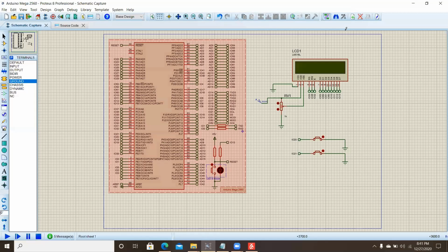Now moving towards our next lab, which is lab 7. In this we will learn about the external or PC interrupts in ATmega328P. Basically, the first type of device interrupts are called external interrupts, and these interrupts are called on a given status change on the INT pin. This is essentially an input interrupt and is great to use for applications where we might need to react quickly to an outside source, such as a bumper of a robot hitting the wall or to detect a blown fuse.